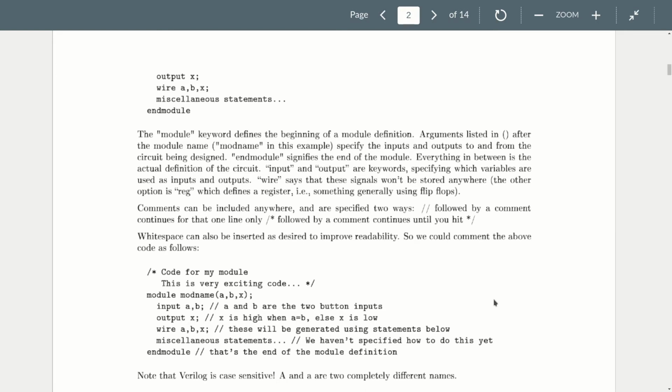So you can put comments in Verilog, and I strongly recommend getting in that habit, right? And if you're doing 224 with me next fall, you're really going to want to get good at making comments. So you can do comments like you do them in C. You can say /*, put in a bunch of comments, and then a */ at the end. So you can have multiple lines. Or you can just say // and everything on that line becomes a comment.